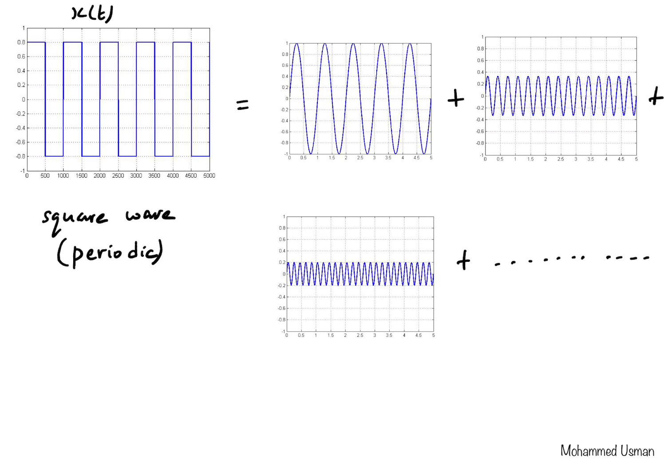So basically what we find is that a square wave signal is the sum of a 1 hertz component plus a 3 hertz component plus a 5 hertz component plus 7 hertz plus 9 hertz and so on. In fact in this case we have to add an infinite number of terms to get back this exact square wave shape.